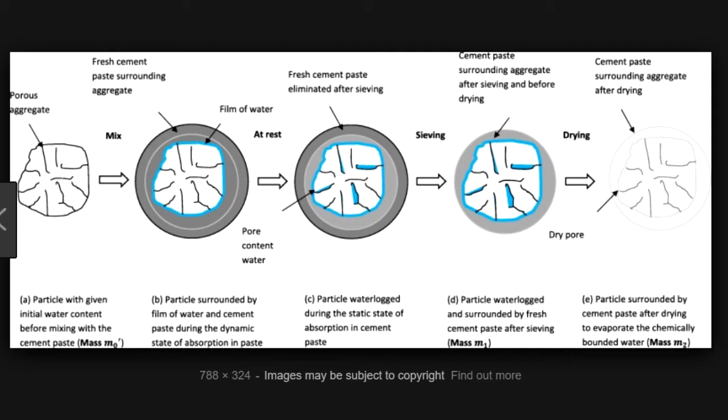For the fine aggregates, the amount of sample collected was placed on a pan to pile up and was then flattened out to form a circular figure. The figure was then divided into 4 sections. 2 sections opposite to each other were removed. The other 2 remaining sections were placed in a container. The container with the sample was weighed and then placed in the oven to dry.